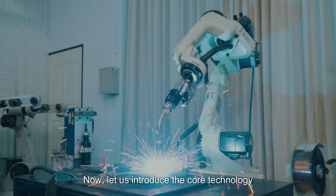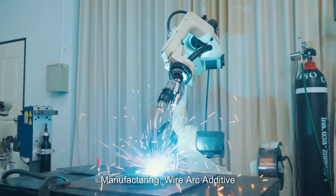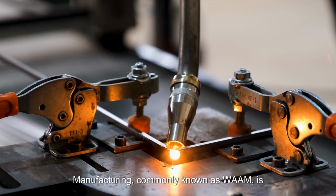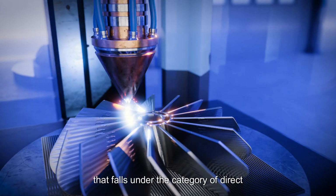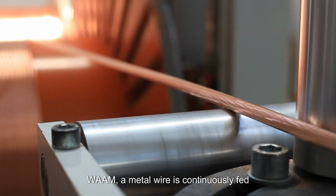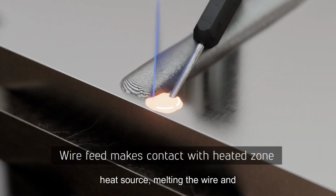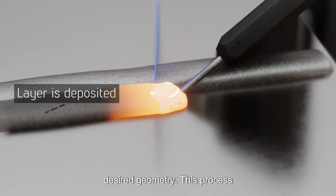Now, let us introduce the core technology used in our project, wire arc additive manufacturing. Wire arc additive manufacturing, commonly known as WAM, is an advanced metal 3D printing technique that falls under the category of direct energy deposition processes. In WAM, a metal wire is continuously fed into an electric arc, which acts as the heat source, melting the wire and depositing it layer by layer to build the desired geometry.